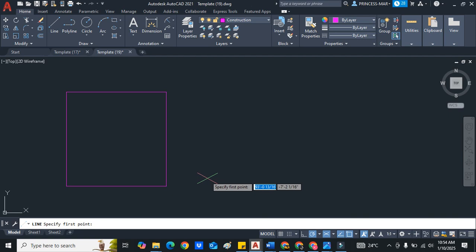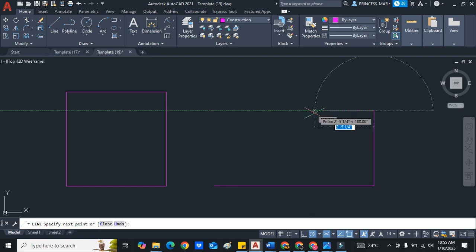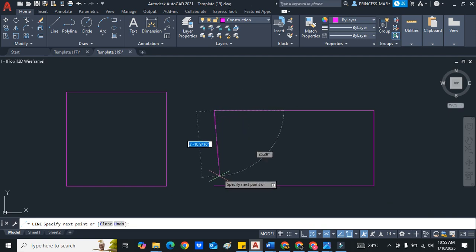I'm going to draw a rectangle. So click line tool, left click anywhere. So I'm pulling across. Let's do this at 80, enter, straight up, do it at 40 going up, 40, enter, and I'm not left clicking anything on the mouse right now. I am only typing in and pressing enter. And when I pull it down to the bottom here to end it is when I left click. To turn off the tool, we press escape.